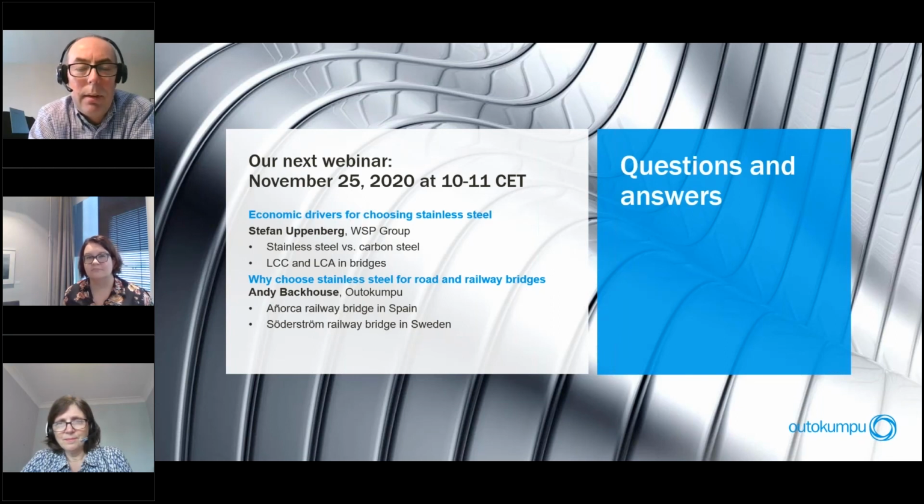The principles in the Eurocode are: assess where the salt is, assess where the pollution is, assess rainfall and humidity. Those principles are valid wherever you are in the world. So the principles can be applied in that sense, but for an environment outside Europe, it would be important to take account of the specific non-European conditions of where the bridge is located.